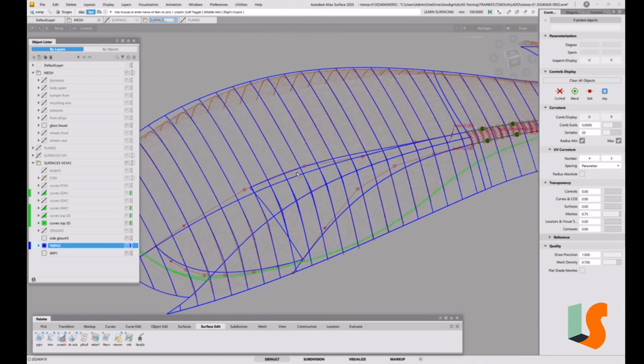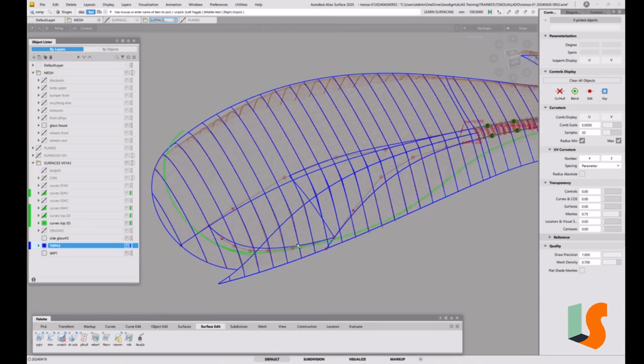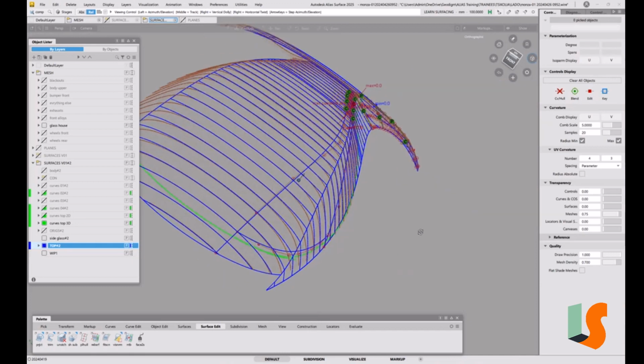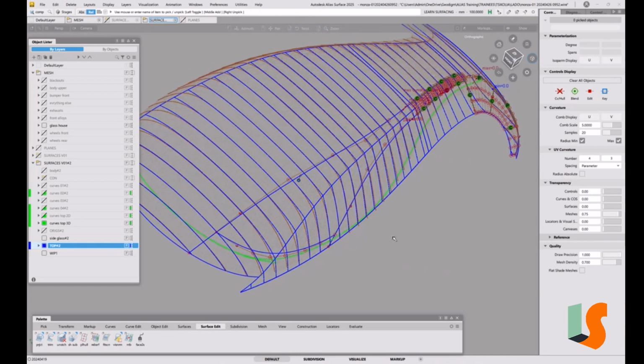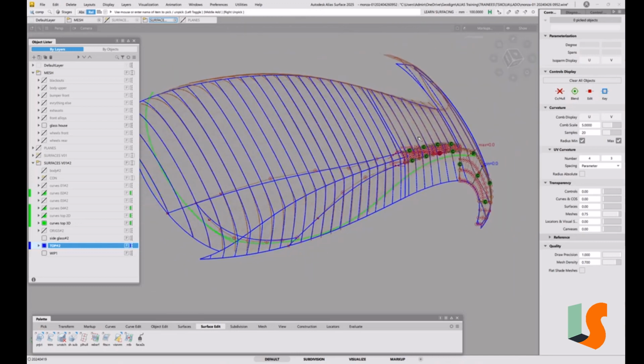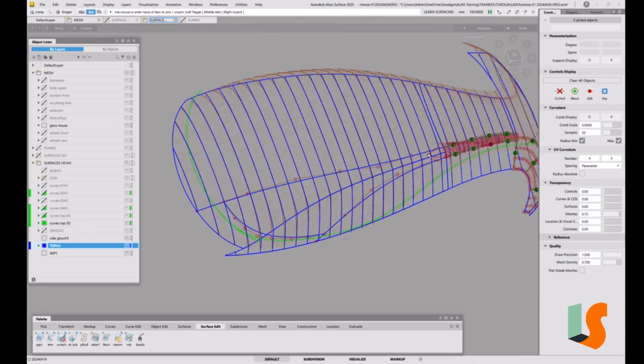And so we're going to use these curves as the basis of our surface. We're going to get rid of this fillet that we created, because that was just to see roughly where that other edge might be, but it didn't mean we had to follow it exactly. Right, so now we want to get a surface in here, and I'm probably just going to use square, which means we need 4 edges. So we've got this edge, and that edge, but we need another edge here.